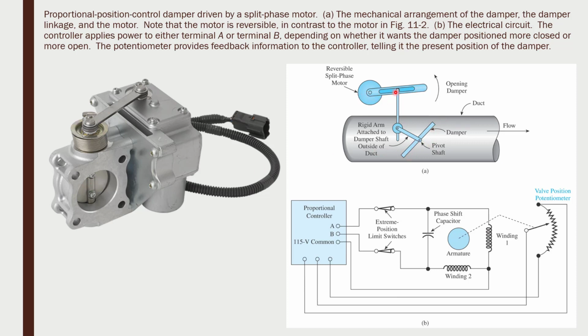And my motor driven components here. Instead of rotating around 360 degrees, this one opens and closes just every 90. So when this is straight up and down, the valve is closed, as is shown here. But if this were to open 90 degrees, then that's going to allow the maximum flow.